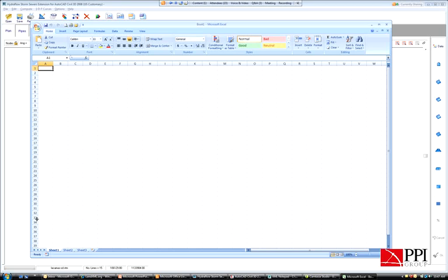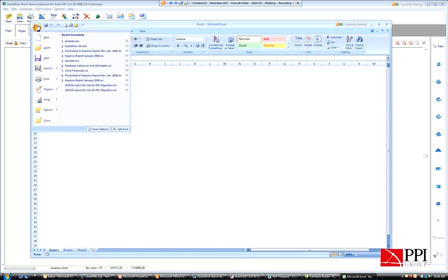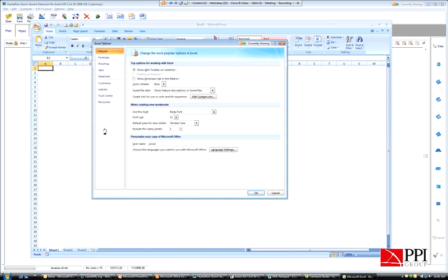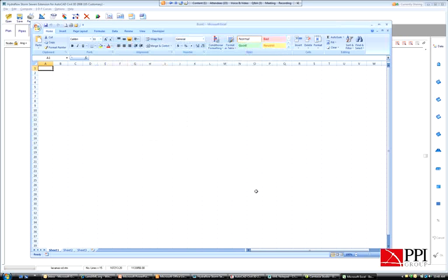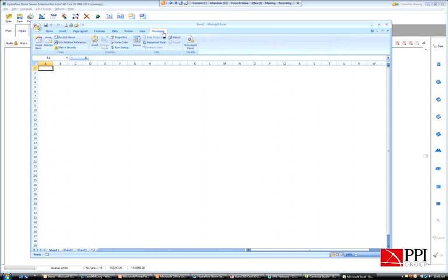And so what I'm doing, like we saw, it's a LandXML 1.1 schema that you want to be attached to. And the way to get that in, the first thing you're going to need to do is come in here to Excel options. I clicked up here and came to Excel options. I want to show the developer tab in the ribbon. In this LandXML schema, it's a .xsd file. I can provide you with the link, but landxml.org is where you download this. So now I've got that developer tab open.